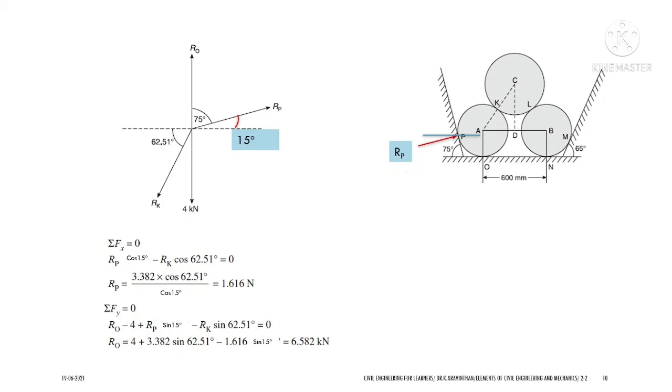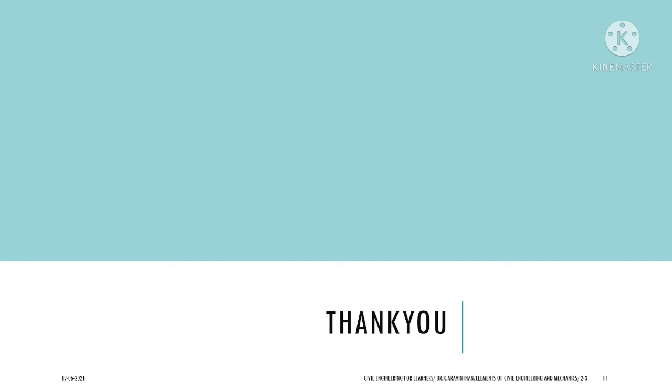Always you will be having a self weight of an object. So you have to consider the self weight of the object and the surface point of contact, whatever might be the object. And if you have a strong geometry concept, the geometric property of lines and angles, it will be easy to identify the angle of the force and the angle with the horizontal axis. If you know how to find this, you can use either Lamy's theorem or the equilibrium equations in order to find the support reaction.